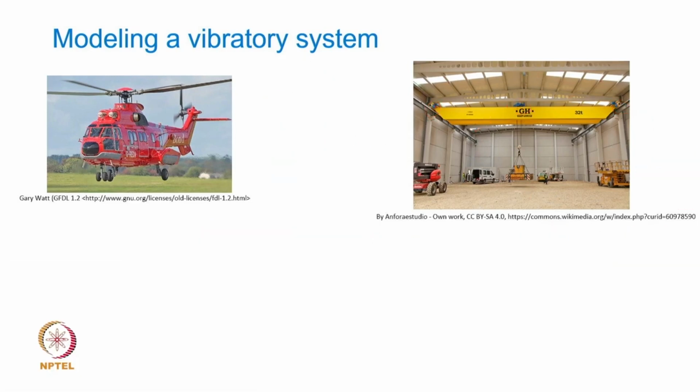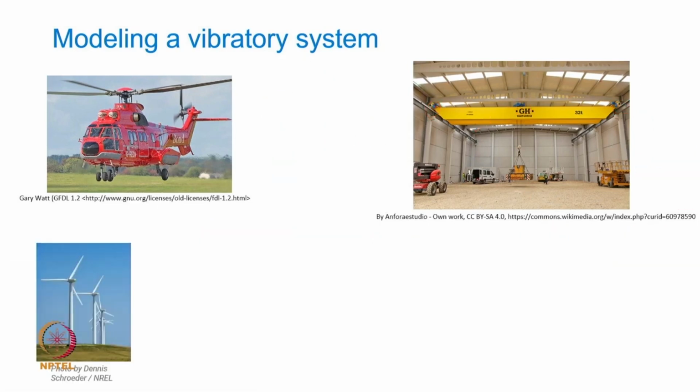Okay, the final example that we may consider here is that of a wind turbine system that we earlier talked about. Again, if I want to model this as a simple single degree of freedom system, supposing that this is a vertical longitudinal vibration problem, this column would again be modeled like a spring, isn't it. If it is modeled like a spring having some stiffness, with the mass of the nacelle sitting at the top, and this is a longitudinal vibration problem, then the stiffness has to be appropriately calculated. That of course will depend upon the material properties and the shape and size of this particular column.